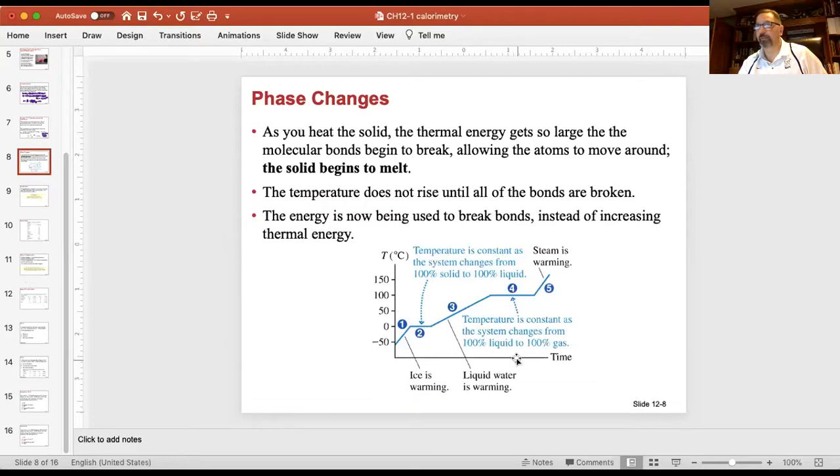And you can see the x-axis is time, right? This is happening over time. And so along curve 3 here, what we're doing is we're adding heat to cause the temperature to increase. And eventually we get the temperature of the water to 100 degrees. And when all of the water is at 100 degrees Celsius, the water starts to boil and the liquid phase goes into the gas phase, steam. And that happens along curve 4 right there. And until all the water is converted into steam, the steam also in contact, in thermal equilibrium with the water, stays at 100 degrees C.